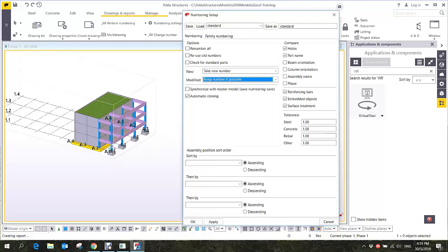That's what I was trying to say earlier: if you are following the consultant's prefix, then it's okay. Let's say all the column prefixes are PC, PC, PC, PC, and they don't care about the numbering of 1, 2, 3, 4, 5. Then you can use the Tekla Structures numbering system. That will be good. But sometimes they put, let's say, K1F2, K1F-3. So that 2 and 3, you don't know how to follow. But Tekla Structures will give you K1, F2, 3, 4, 5 continuously, a running number.